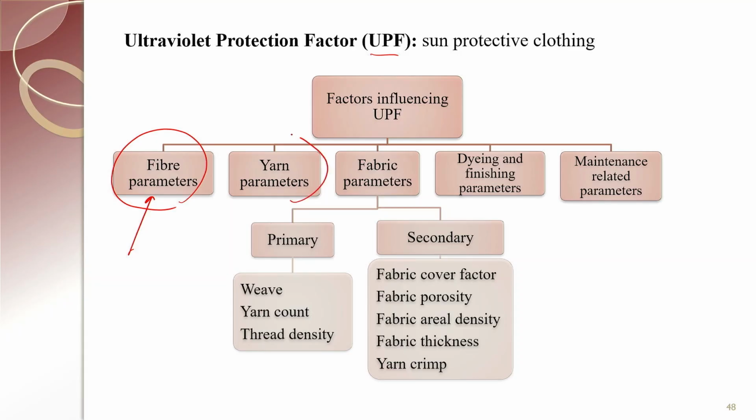Yarn parameters, like yarn twist, yarn porosity and yarn linear density, affect the UPF value. Fabric parameters are there, typically the primary parameters: the weave, yarn count and thread density.